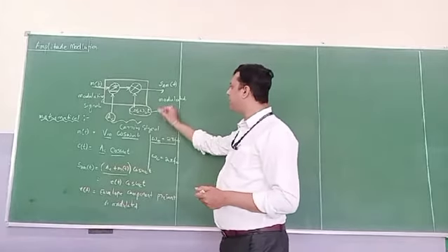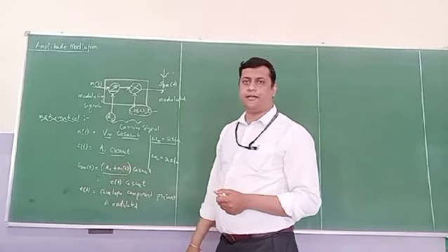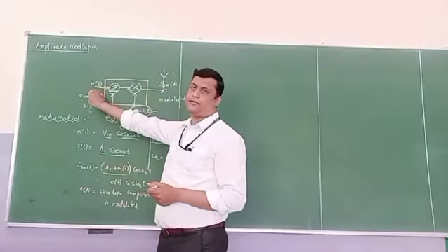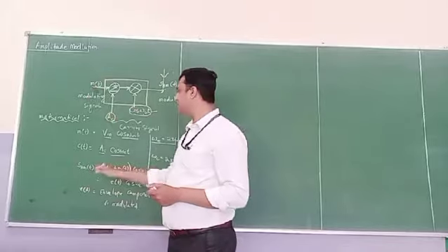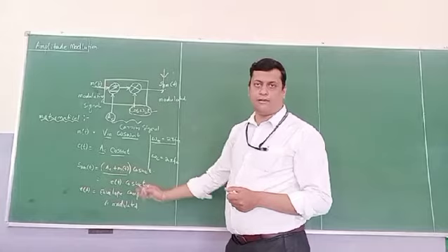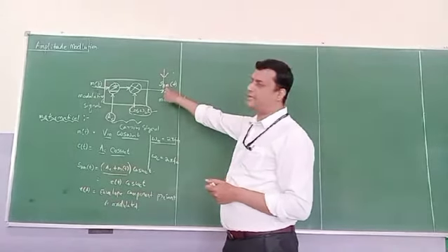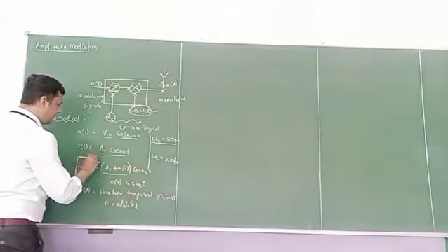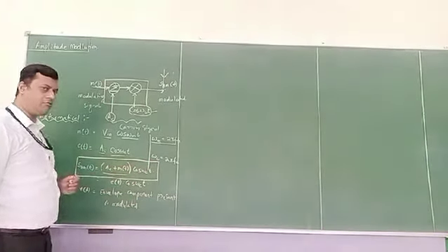So at this point, you can see AM signal is generated. AM signal itself indicates what? Here the variation of the amplitude of a carrier is done with respect to the instantaneous variation of the amplitude of modulating signal. So for that I have written this. Now if I am going to elaborate this equation, these all equations are trigonometric equations. So mathematically we have represented AM signal with the help of this s suffix am of t, which is equals to AC plus m of t into cos omega ct.